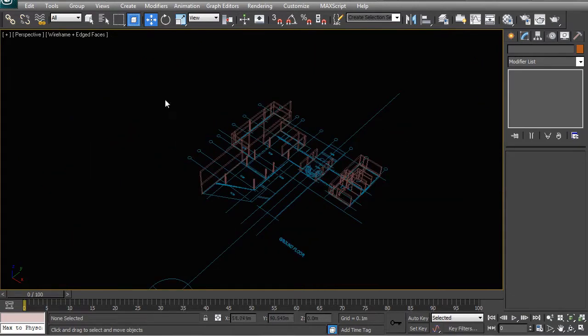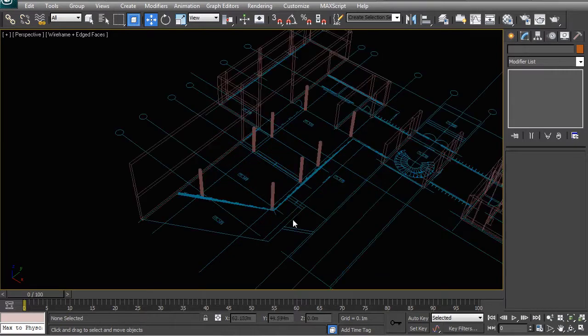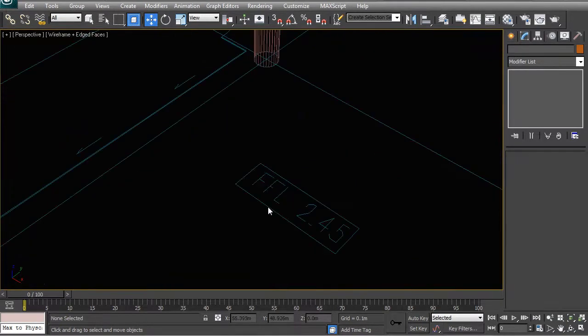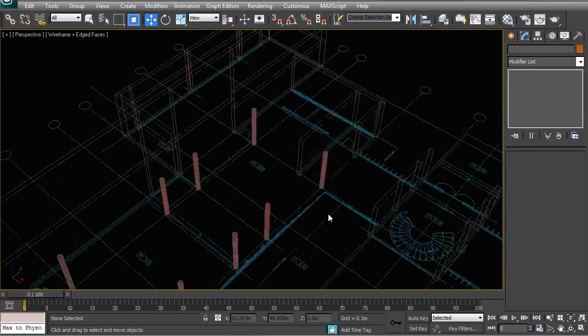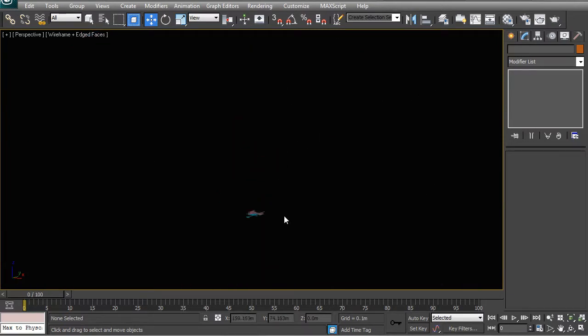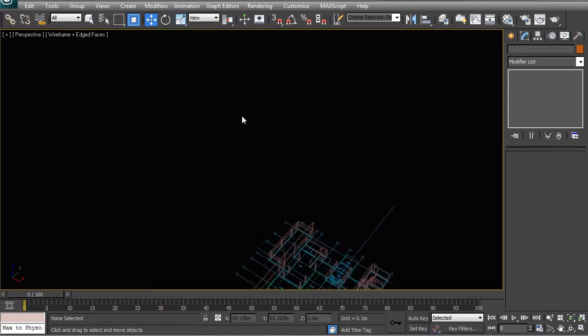As we had already modeled the contours, the same rule applies. Where you see 0, 1, 2, 3, 4, 5 meters on your contours, make sure that those same heights are represented in 3D. It's just going to make your life a lot easier. Now let's say you have a situation where you are using a very high number, for example, 125.45. What you could do to simplify things is subtract 100 from absolutely all of your numbers. It would be a global subtraction, because you don't want to model way up there in your model space, as it's going to end up having very odd numbers for you to work with.